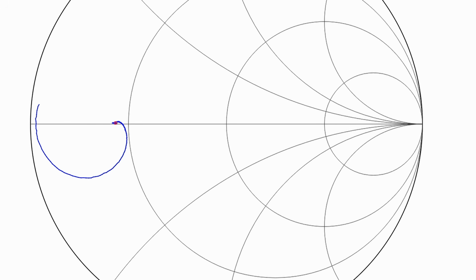And this is what the VNA shows us without any effort. For example, we see that the curve crosses the middle line a second time at 1 MHz, in addition to the 10 MHz we saw before. And it nearly hits the short position at 20 MHz. So our potentiometer and capacitor behave like a piece of copper at 20 MHz.